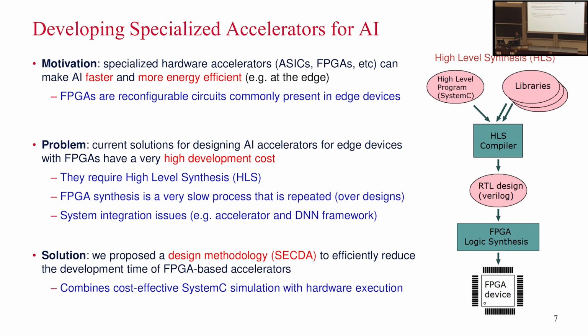So in order to not program at very low level, like VHDL, what we have is high-level synthesis. High-level synthesis is very slow, right? If you want to propose a design and iterate over and over, synthesizing the design every time is super slow. In the board that we are using, that I will show you later, every synthesis takes 1 hour. So typically we can have 15, 20 iterations to get a design that actually meets our needs. So this is very slow.